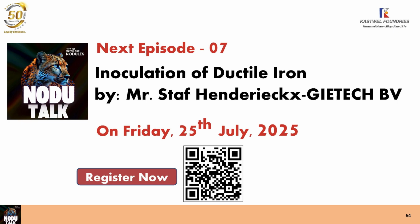Many times I hear from foundry owners, yes, sir, but if you design our pouring system, it costs much more. And then my question is, what costs more? A more expensive pouring system or a scrapped casting? That's the decision you have to make. And a good pouring system for ductile iron is not very simple. It must be pressurized, non-pressurized. It must hold the first metal, and the active magnesium must be low, and then you will have very few to no problems of dross.